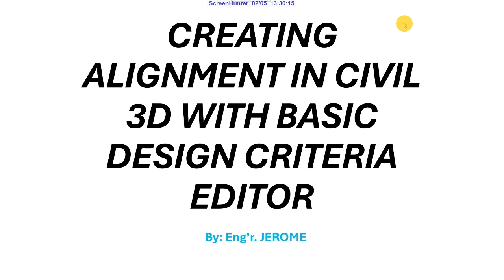Today I'm going to show you how to create an alignment in Civil 3D. Now, alignments in Civil 3D are fundamental, intelligent 2D and 3D objects that define horizontal centerline paths or linear geometry for design projects such as roads, railways, and utilities. Its foundation is critical because it establishes the baseline from which all other design elements, such as profiles, corridors, and cross sections are derived. Now take note, guys, we cannot create our profiles and cross sections unless we first create our alignments.